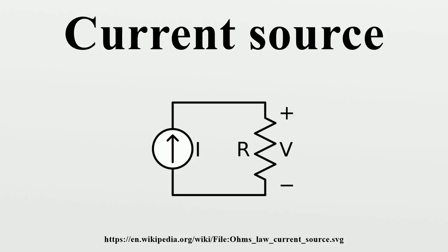Current sources with negative feedback. They are implemented as a voltage follower with series negative feedback driven by a constant input voltage source. The voltage follower is loaded by a constant resistor acting as a simple current-to-voltage converter connected in the feedback loop. The external load of this current source is connected somewhere in the path of the current supplying the current-sensing resistor, but out of the feedback loop.